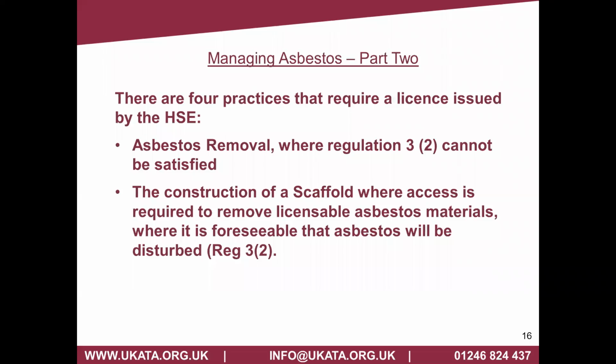However, if the scaffold by assessment is not likely to disturb it, but they are still putting that scaffold up for licensed contractors, then the scaffolder wouldn't need to be licensed, and a normal scaffolder could be used. So it's where it's foreseeable. So it's all about the risk and the assessment of that risk.